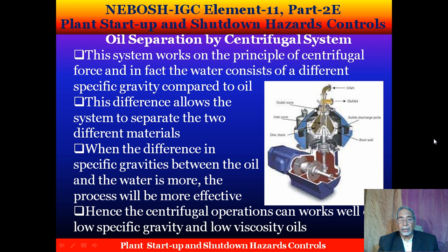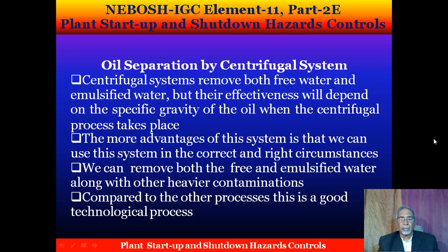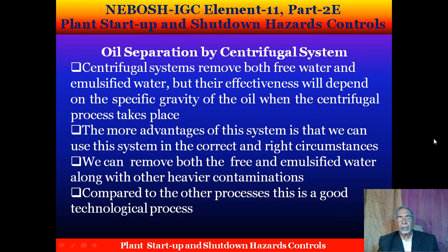When the difference in specific gravities between the oil and the water is greater, the process will be more effective, as centrifugal operations can work well on low specific gravity and low viscosity oils. This centrifugal system removes both free water and emulsified water, but its effectiveness will depend on the specific gravity of the oil.